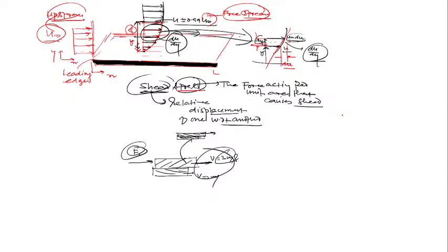and these particles act to retard the motion of particles in the adjoining fluid layer, which acts to retard the motion of particles in the next layer, and so on until a distance y equal to delta from the surface, where the effects become negligible. Effect of what? Effect of the surface boundary. And this reduction of fluid motion is associated with the shear stress, right?